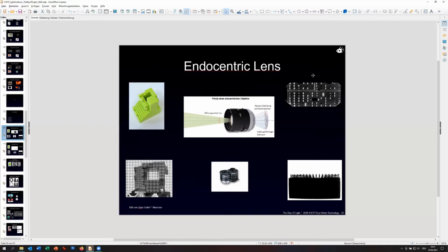Here on the right side, I have this connector. You see a lot of solder pads on top. And if you look from the top, of course, maybe they are on the same line, but we have to see if they are really on the same line. We would do it the same way with the eye. We put it in front of our eye, and we look exactly at this one, and then we move it, or move our head a little bit, look at the next, and so we go through all the rows, and we will always see, like in the center, how it looks.